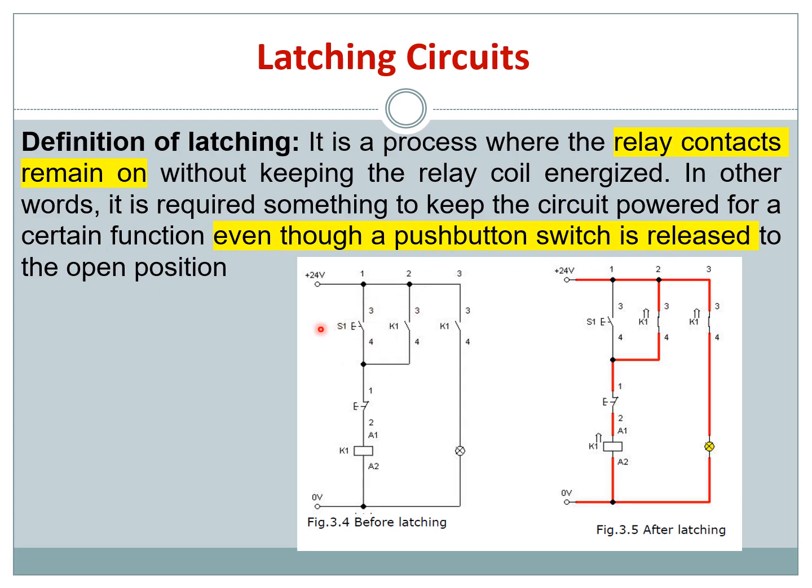Normally, to start a circuit, you need to press a push button, and then it will be connected. When you release the push button, since you have a spring inside, your circuit will stop. But in latching, even though you press once and release the button, it will stay connected until you press the stop button. So that is what we call latching.